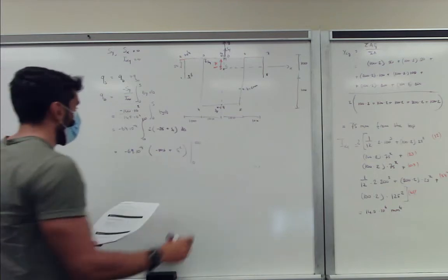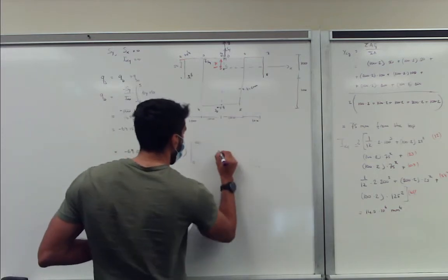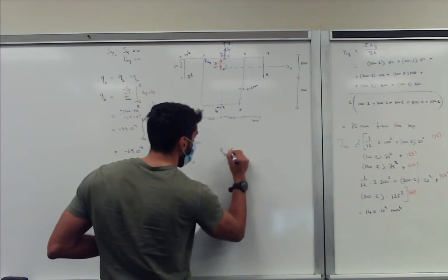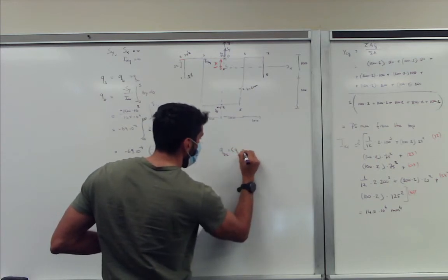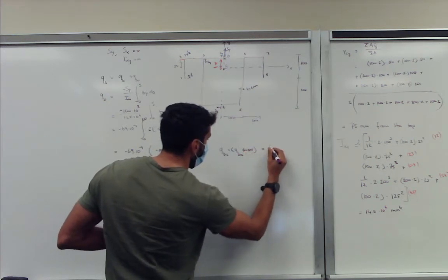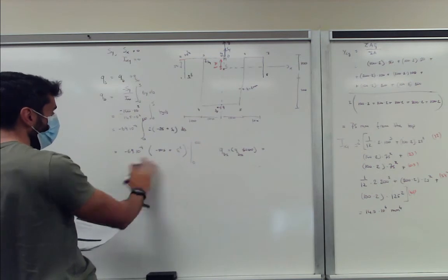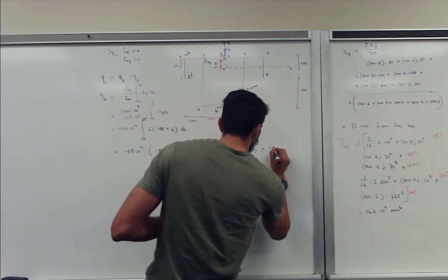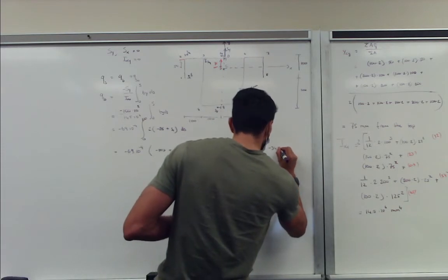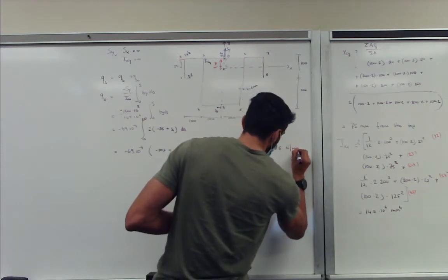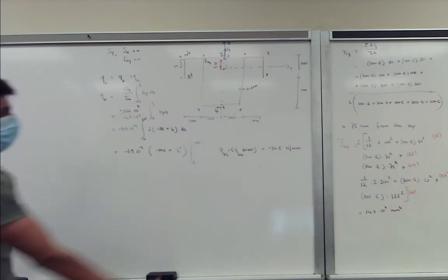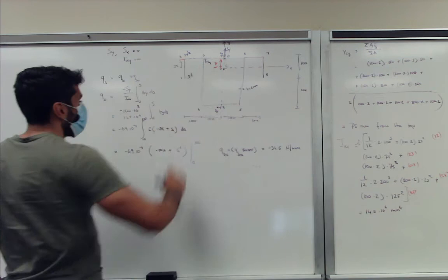So now we have to evaluate point 2, so QB2, which is QB12 at S equal to 100. That's plugging in 100 and evaluating this equation. I would get minus 34.5 Newton per millimeter. And this will be our starting point from point 2 to point 3.